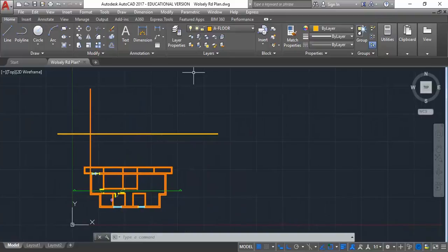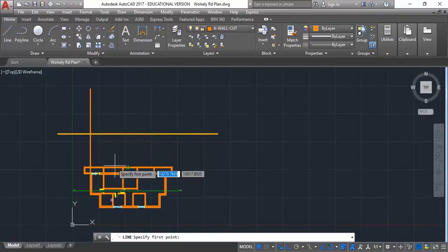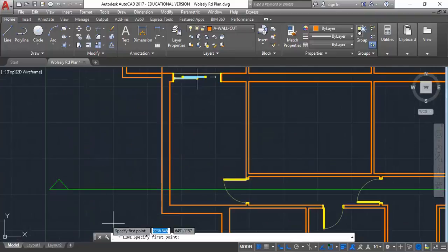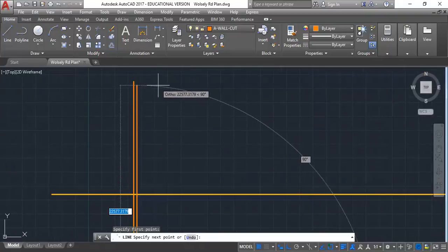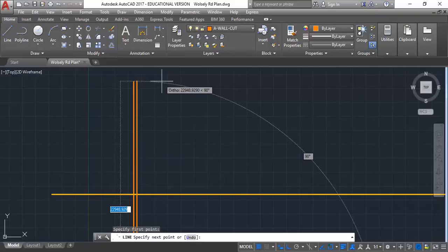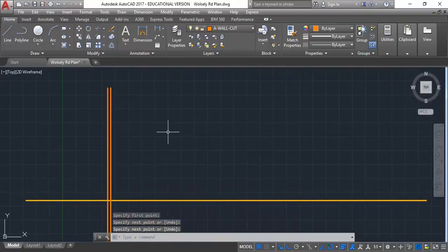So now I might go and draw another line on my wall layer, from the inside. So this is where the section line crosses the same wall but on the inside. I'll just take it straight up again, so it's parallel to the first one, but I don't know how high to take that yet. So this is where you might have worked it out a bit more than me. Has anyone worked out the ceiling height? You've done it 3 metres? Good. Yeah, that's what I was going to do anyway, so that's good.